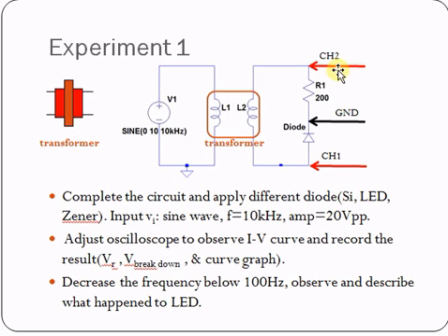This will enable us to observe the voltage across the diode by channel 1. The channel 2 gives us the voltage across the known resistor, which enables us to calculate the current passed through the whole circuit. Note that because we're measuring the voltage in the opposite direction of the current, we have to invert the input of channel 2.